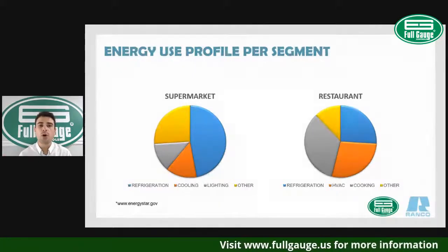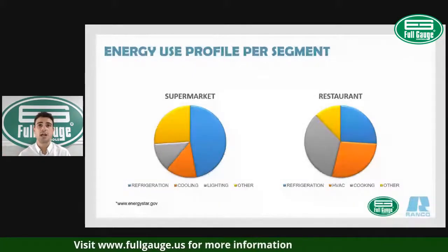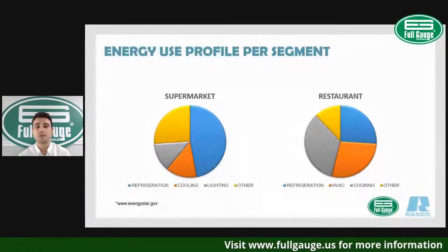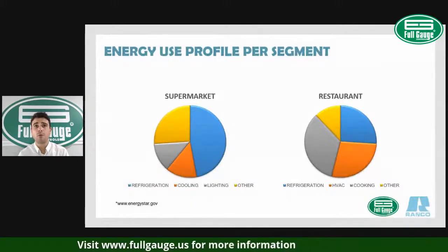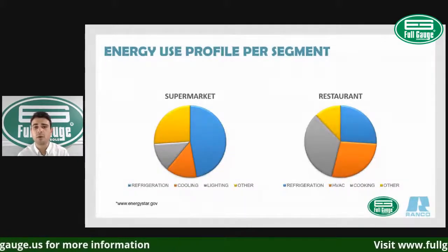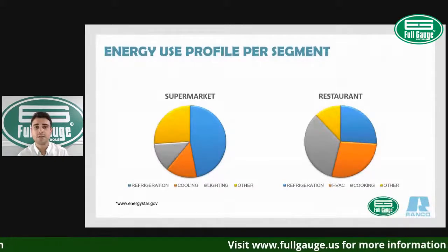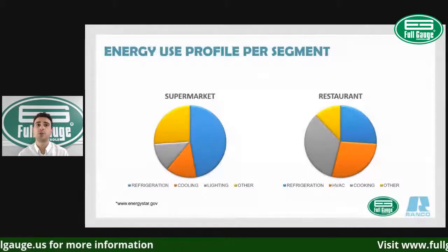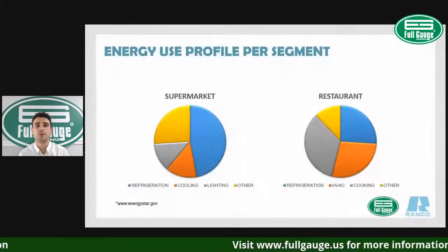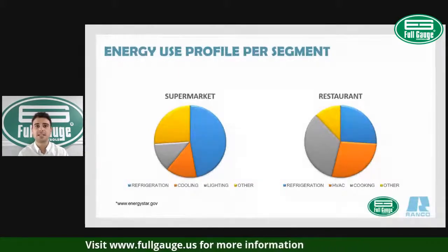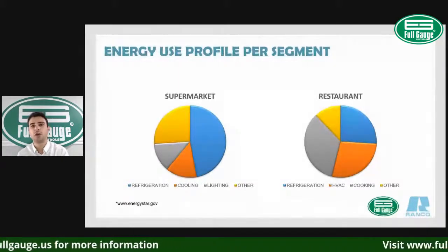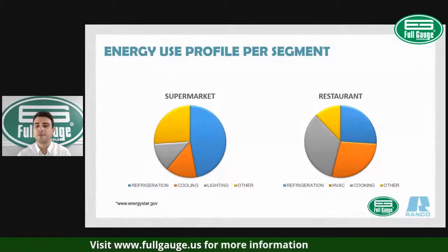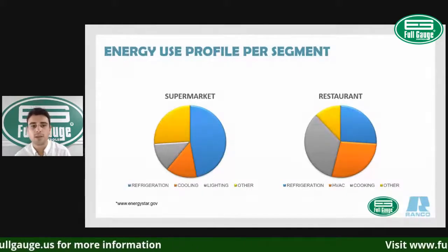So the selling point here is, first, you're going to have a better temperature control product. Your products will be kept within better temperature ratings. So food safety is the first selling point, Michael, that you can bring to your customer. Food safety. In addition to that, energy savings. You can save up to 20% energy just by switching from a mechanical thermostat with a time defrost to an electronic controller that will control that process based on a microprocessor and have energy efficient defrost within it.